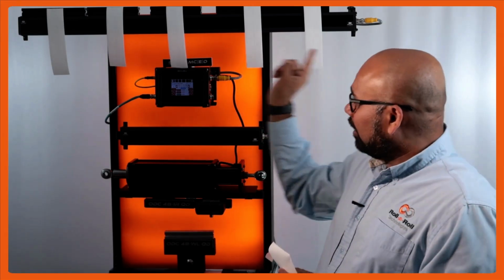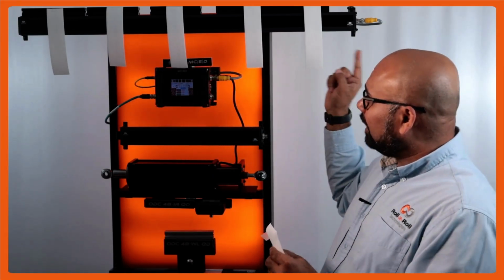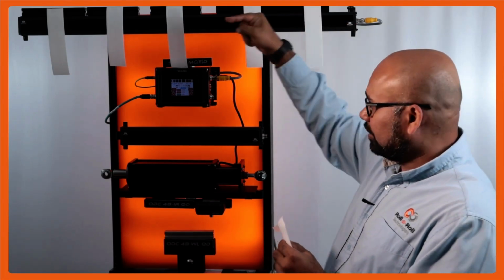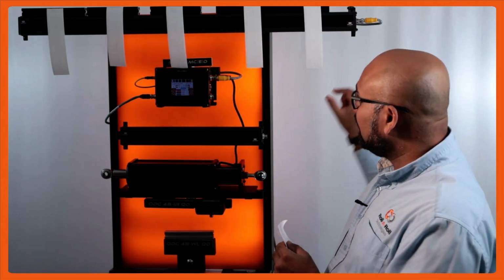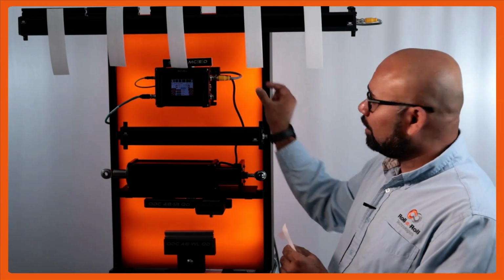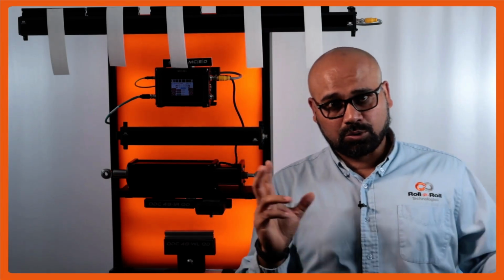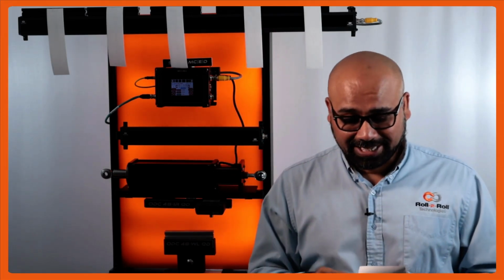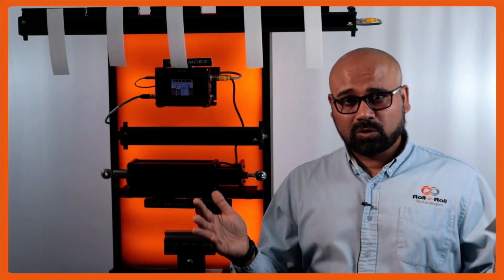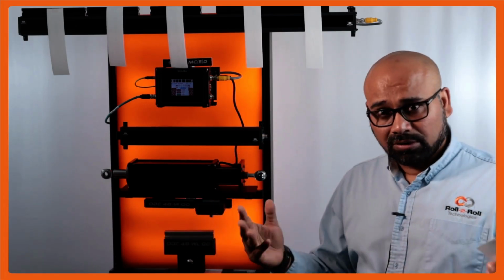Ideally, the camera is just a line, but you have two sensors in there, so there are two rows. We want the web to be perpendicular to the two rows that we have. Now, it's impossible for somebody to install it exactly perpendicular, so we have that compensation available there. I will show you how we can take care of that.